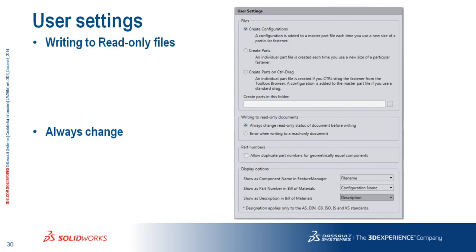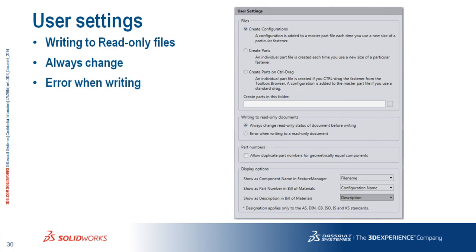Unless, of course, you check the other box. Instead of always change, you have error when writing. Then you won't get the uncheck option, and you'll probably get a bunch of calls, why can't I add a configuration to my part?